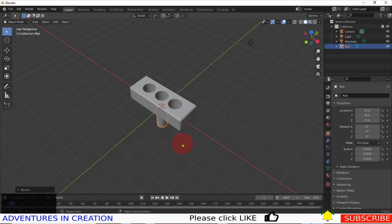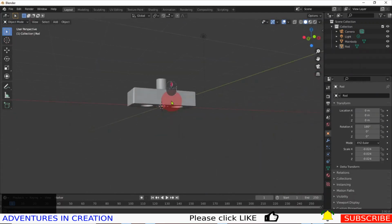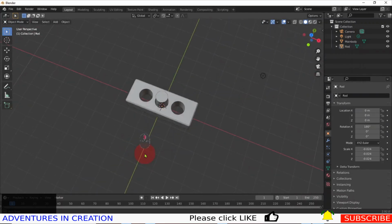Now, if I'm turning 180 degrees, it doesn't matter if I do it in the X or the Y. So to rotate in Blender, it's just R. And then you can tell it which axis you want to rotate on. So I'm going to just say X, and I'm going to rotate it like that. And if you look over to the right, you can see that I rotated it 179 degrees. So what I'm going to do is pop that up just one more. 180 degrees. So there we have the rod is now the right way up for the way I wanted it.